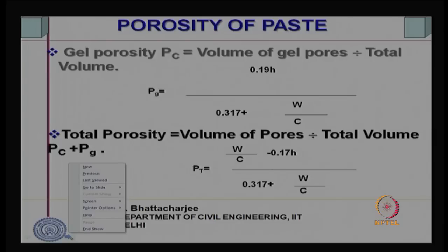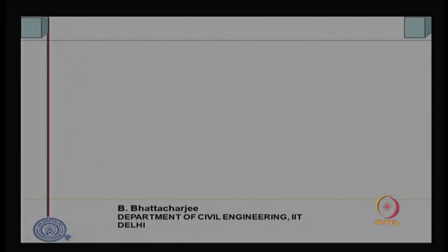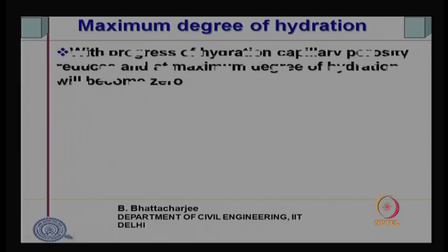Right. Now, the total porosity of cement paste is important, but one interesting thing is that for complete hydration, I can derive the minimum water cement ratio required from these concepts.